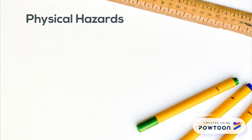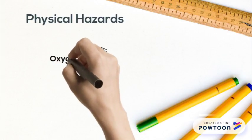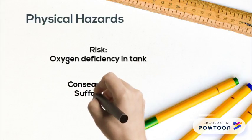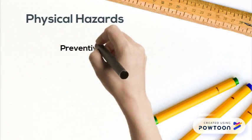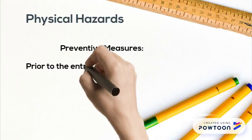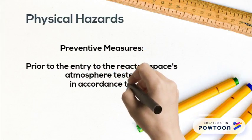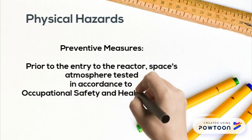As for physical hazards, workers entering tanks may be exposed to confined spaces with oxygen-deficient atmospheres. Prior to entry into tanks or vessels, testing of atmospheres within the space should be required and be in accordance with the Occupational Safety and Health Administration standard.